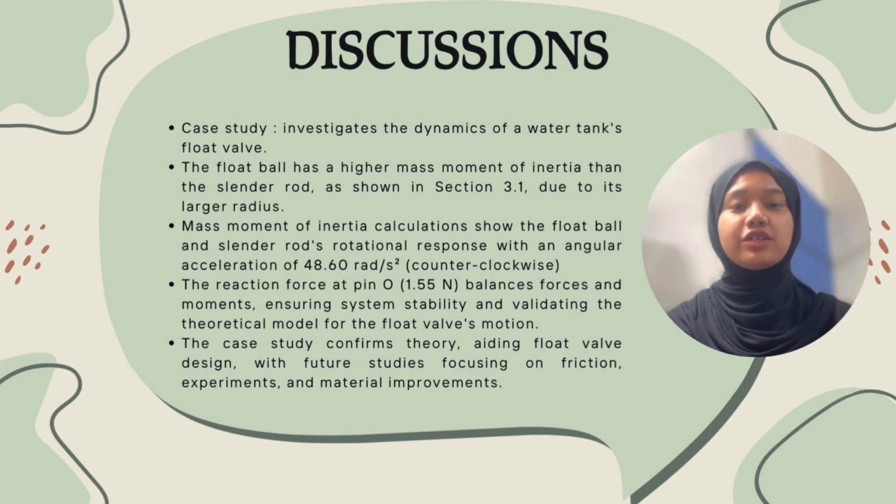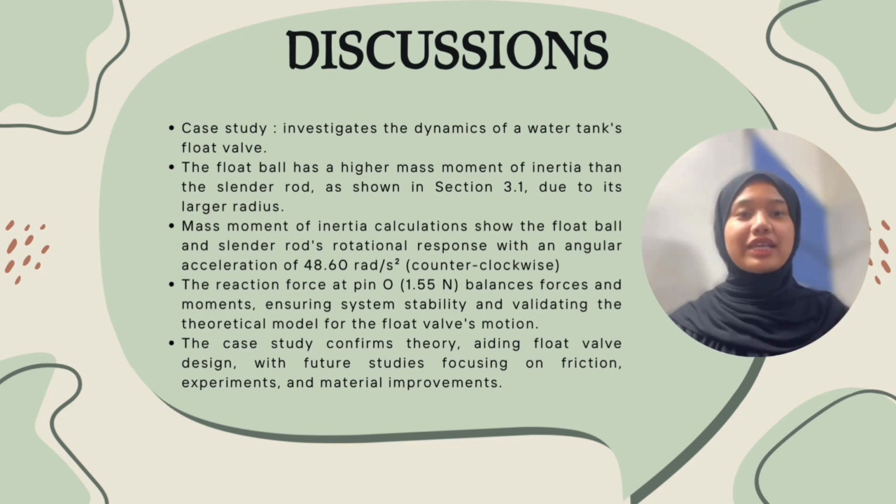The tangential direction of the float ball and the slender rod was also taken into account, resulting in an angular acceleration of 48.60 radian per second square counterclockwise, indicating the rotational response when torque or external force is applied. The reaction force at pin O, FO, equals 1.55 Newton, balancing forces and moments produced by the float ball and slender rod, ensuring the efficiency of the water tank's float valve. This balance prevents the system from becoming unbalanced, verifying the precision of the theoretical model used to study its motion.